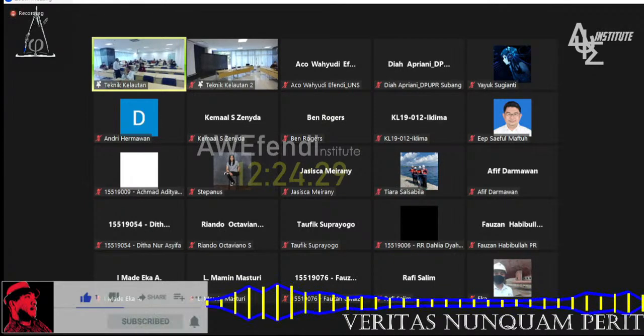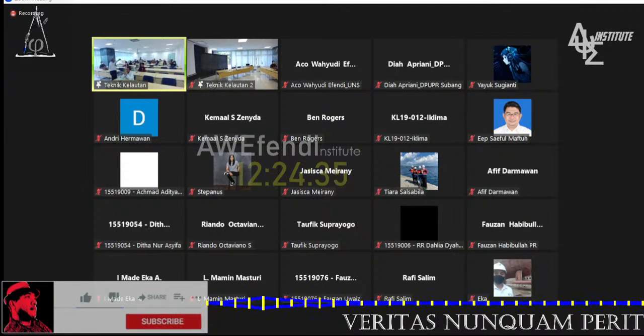The deflector has two functions. First, it blocks the water on the side of the turbine, so you reduce the drag. The drag is also higher at higher speed against the flow, so you block it, and as well you divert the flow towards the other side of the turbine, so you can increase the thrust. So that's the way we try to do it.